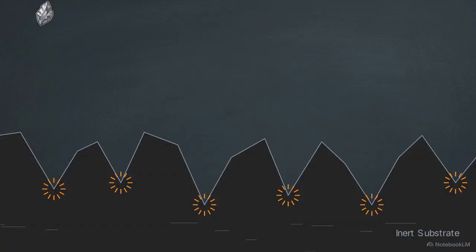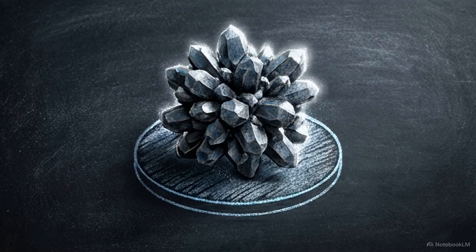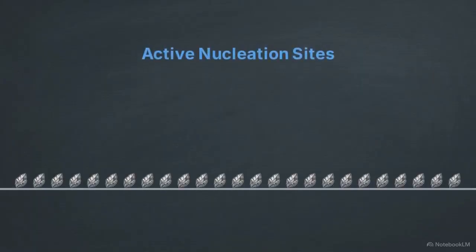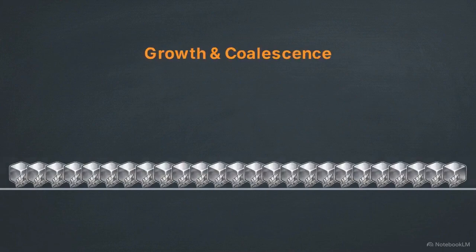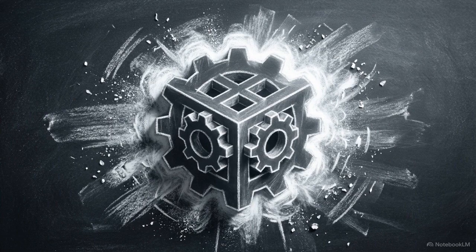During this treatment, palladium particles anchor firmly to the substrate. Palladium is highly catalytic, providing the precise surface energy required to oxidize the first wave of reducing agents. The density and distribution of these palladium nucleation centers dictate how the metal will grow. A higher density of active sites forces the metal to nucleate evenly across the surface, resulting in a uniform coating with a refined grain structure. Surface activation renders a passive geometry into a reactive state, primed to initiate the chemical engine.